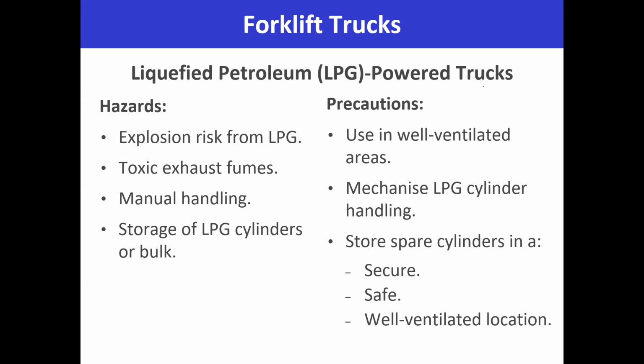Mechanize LPG cylinder handling. This is also very important because LPG cylinders can be very, very heavy and can cause you back pain, injuries, manual handling injuries as well. And you should store the cylinders separately. For example, the LPG cylinder should never ever be stored near the oxygen cylinders. Why? Because if there is leakage of the LPG and leakage of the oxygen, it makes a very combustible mixture and an explosion can happen like that. So you need to store and secure the cylinders, make sure everything is safe, in a well ventilated location as well.